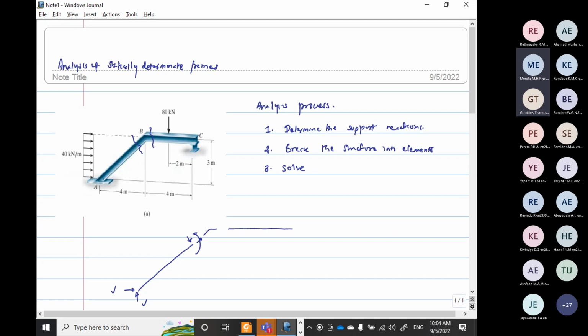So in a rigid section we can have three unknowns. It's like cutting a beam in the middle. You can have an axial force, a shear force, and a bending moment. So if you take that inclined column element, you have three unknowns to solve. Using standard equilibrium equations, we can solve three unknowns. Similarly, on the other side, again we have reactions known. Then we will have again shear force, axial force, and bending moment, and those three we can resolve.